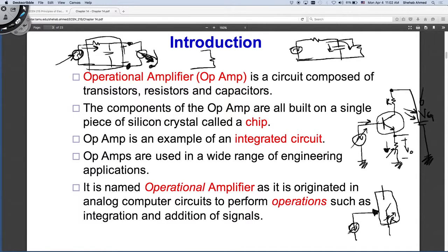This means that I can give a signal for the switch to close. And if I give a signal for the switch to close, this circuit would look like the variable resistor inside my transistor, with this top resistor here, this bottom resistor that I'm measuring the output across, and a source, VG. Does this have anything to do with my sensor? The sensor just gave the control signal to close.